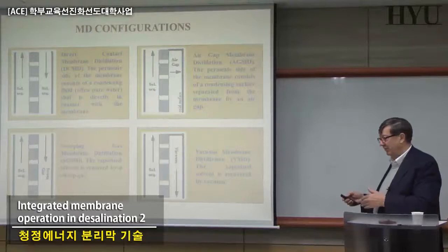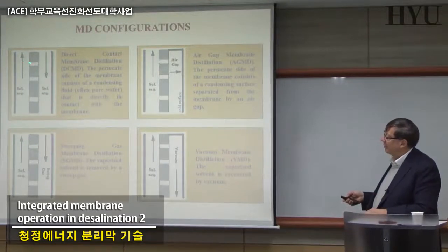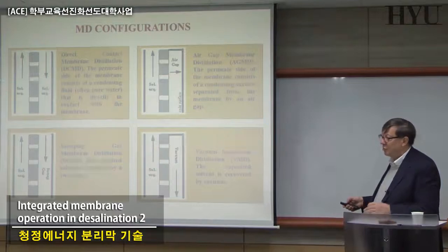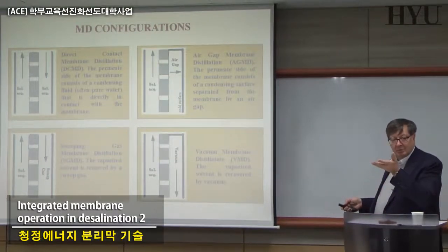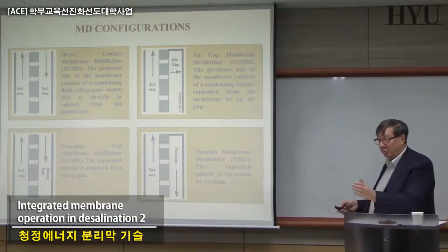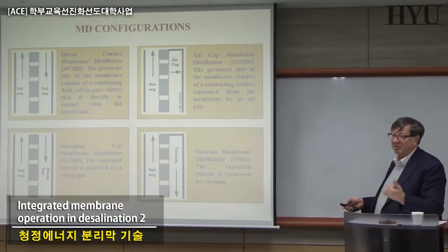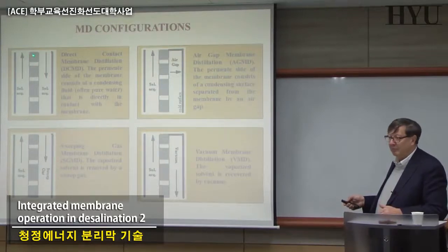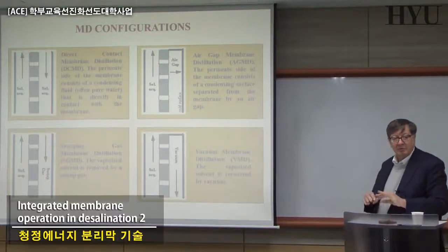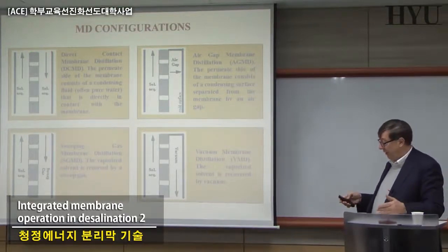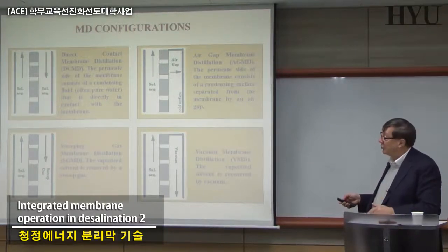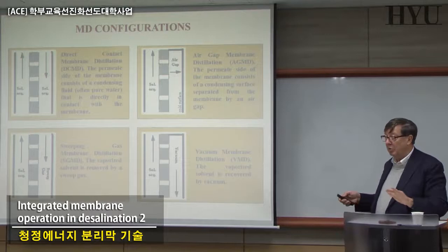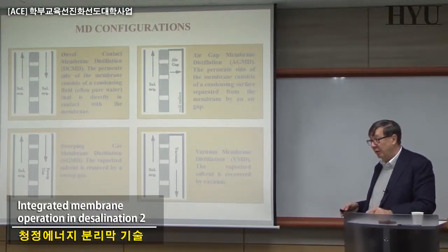We are losing a lot of energy because, due to the temperature polarization and the relatively high thermal conductivity of the polymer, part of the energy we are supplying to evaporate the liquid, instead of being used in the evaporation, is used for warming up the polymer and creating a temperature gradient across it. That is lost. We don't need this. It would be very nice to have membranes in which the thermal conductivity is so low that we don't lose this 50% of energy we are losing today.